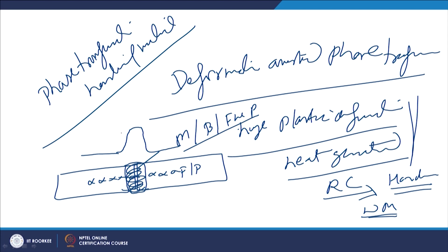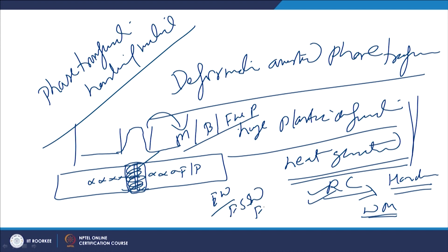This increase in hardness is attributed to the formation of martensite, bainite and fine pearlite due to the plastic deformation and the related heat generation followed by rapid cooling. Processes like explosive welding, friction welding and friction stir welding all lead to property variation in this way.